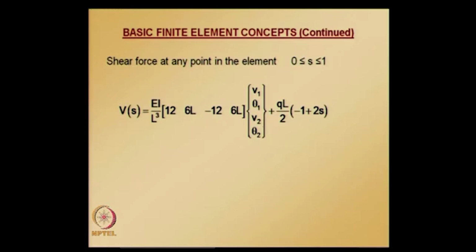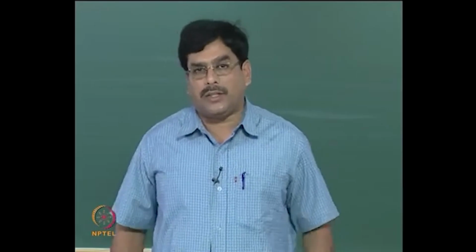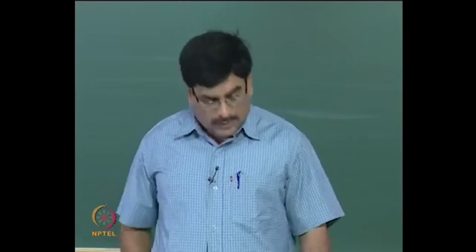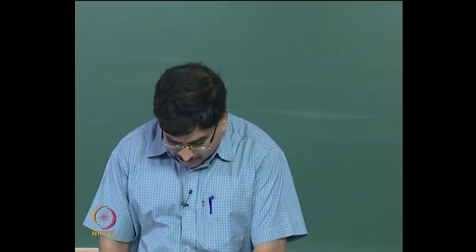And as I mentioned, all these correction terms correspond to a fixed beam with uniformly distributed load, and if you have some other loading you need to add the fixed end moments corresponding to that loading, imagining that each span of the continuous beam is fixed. So now let us take an example.